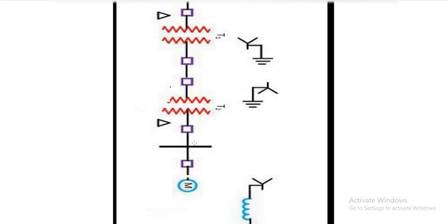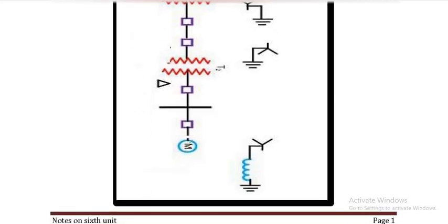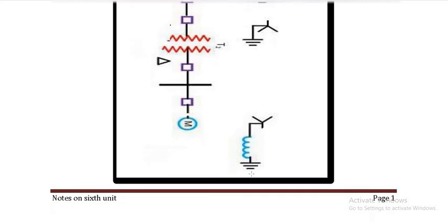Normally when we have distribution systems, we have to have a star connected system, because availability of neutral is really important, isn't it? One more thing I told you when we dealt with three-phase circuits is that the power consumed in three-phase circuits, when it is delta, is thrice the star. So that is one more reason why we use star connection in distribution systems.